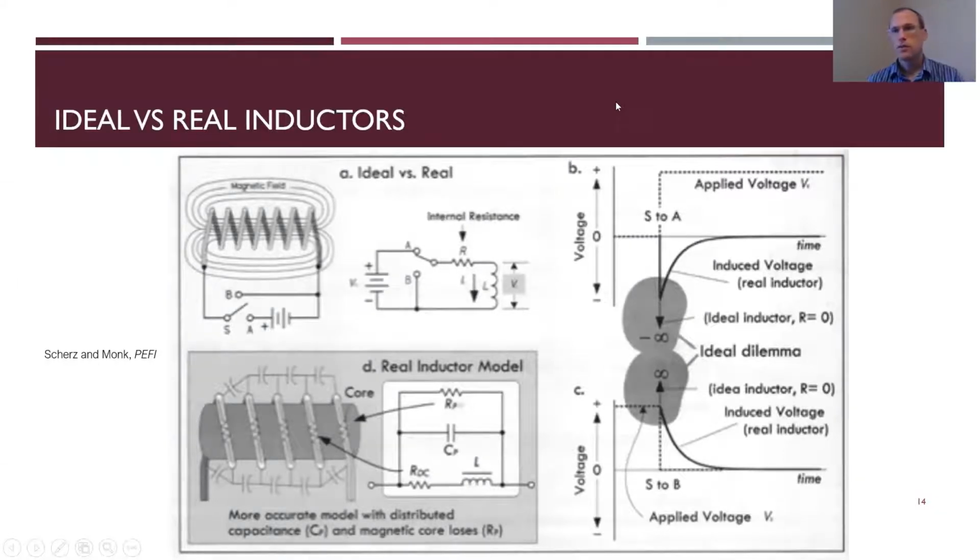So I basically always talk about ideal inductors. So everything we've dealt with before is an ideal inductor. A real inductor is going to have some resistance, mainly because it's built out of wire, and wire, even though it's made out of copper that has very low resistivity, there's still something there. So there's still at least a little bit of resistance in the wire, and especially if you have a really big number of turns, because you have a lot of wire there, that's a lot of length. So you can actually get a decent amount of resistance out of a real inductor.